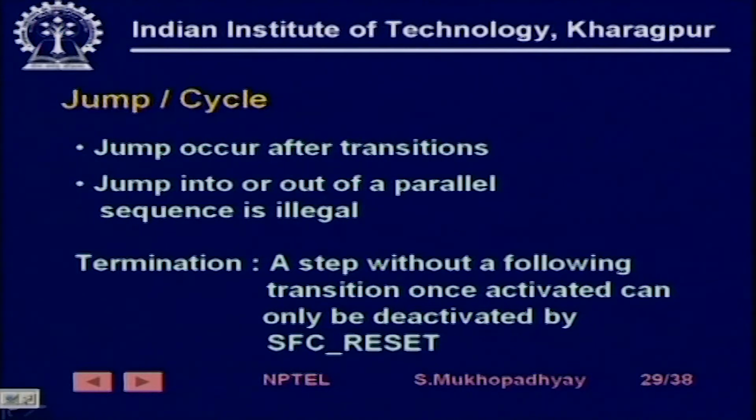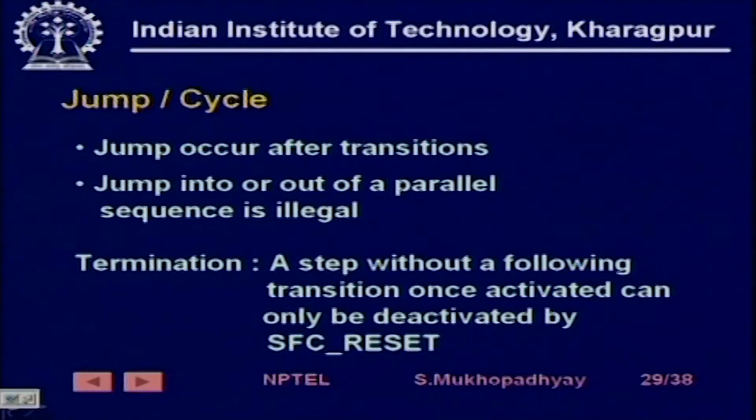Similarly, lastly, you may have termination of a program. That is a step without a following transition. If you have a step out of which there is no transition, then it is a dead state, and once it is activated, it can only be deactivated by a special instruction called SFC reset.